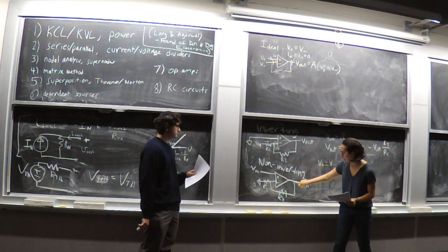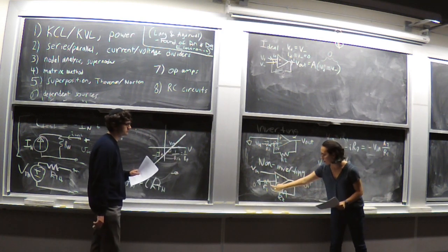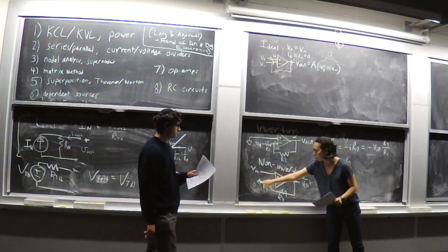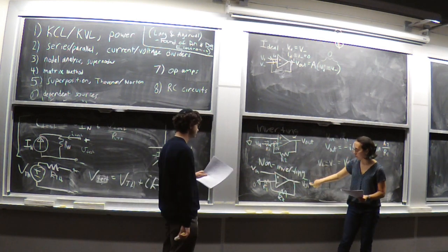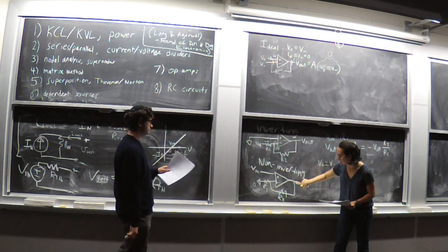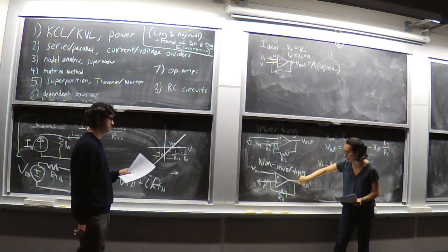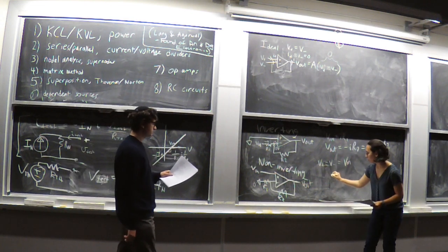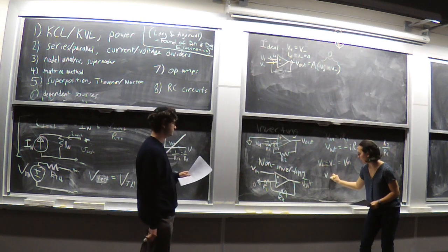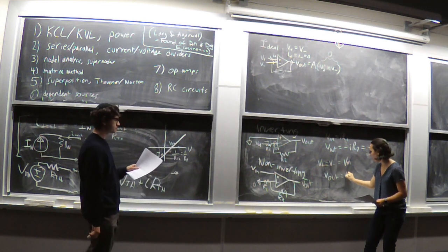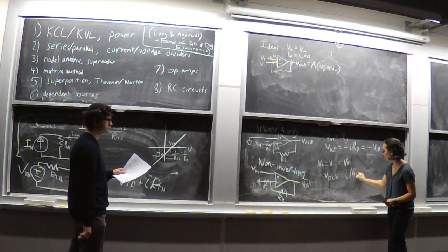as Jacob was saying, the current, in this case, the path is simply from V out to 0. And if we assume V out is positive, then this path will have current flowing from V out to 0. In particular, V out equals I times R1 plus R2.